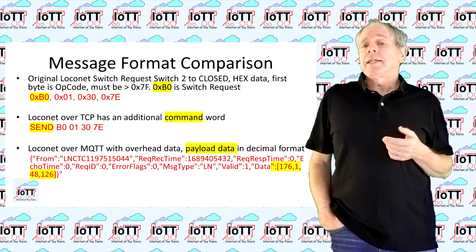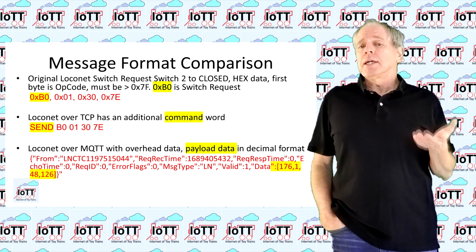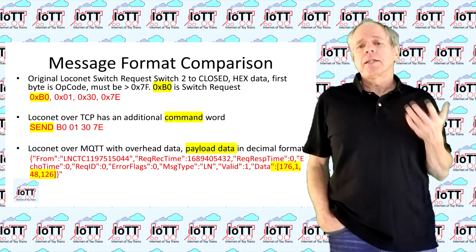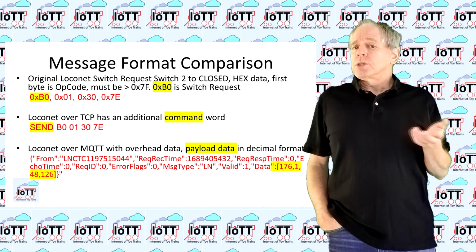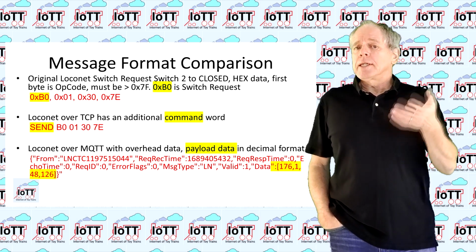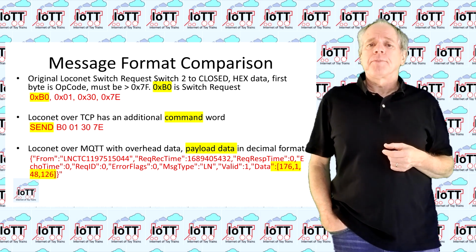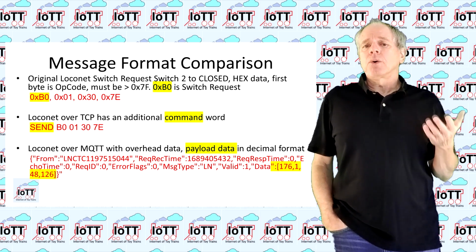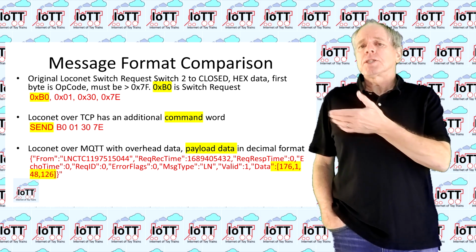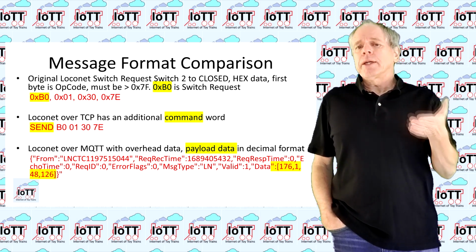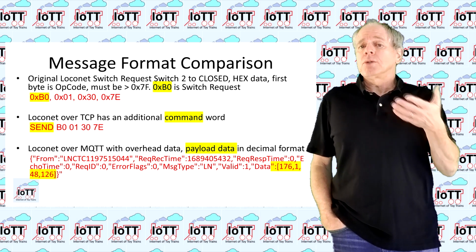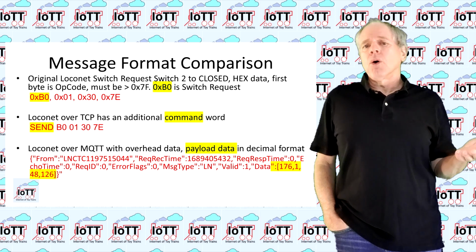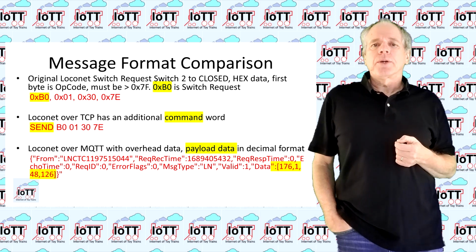Maybe you wonder why the IoTT stick is only using a single broadcast topic, while MQTT implementations like the one in JMRI use separate topics for switches, signals, feedback sensors, etc. The reason is that on the IoTT stick I implemented a Loconet over MQTT message structure that sends complete Loconet messages just encoded into a MQTT format.